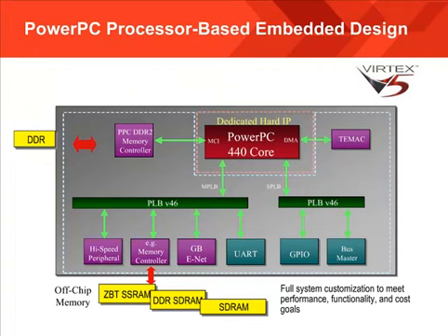This diagram also shows a pretty typical application in which a designer decided to offload some parts of the embedded system to a MicroBlaze processor. In this case, the PowerPC system had its own PLB master bus and also has a shared slave bus that is also connected to a MicroBlaze core. This is done so that the less time-intensive functions can be offloaded to a separate processor. In this example, that is the MicroBlaze processor. The memory controller attached to the master bus can be customized to support ZBT, DDR, as well as other memory component standards. This, like any other peripheral, can be customized to the memory component with the EDK software.